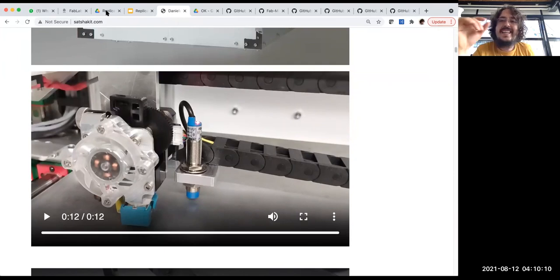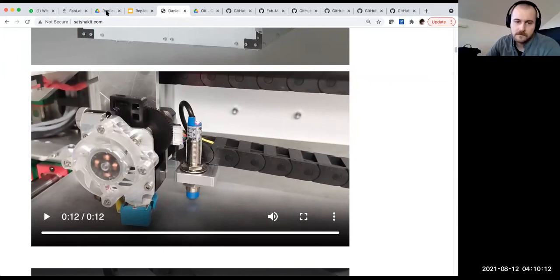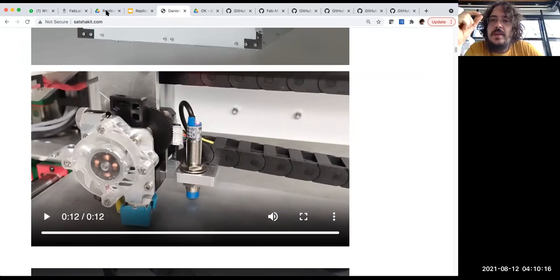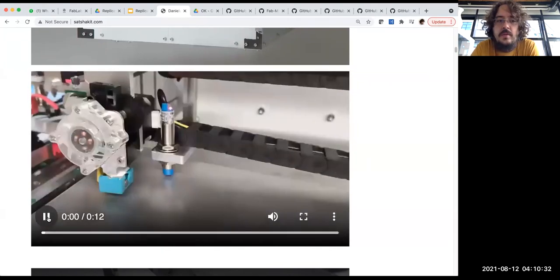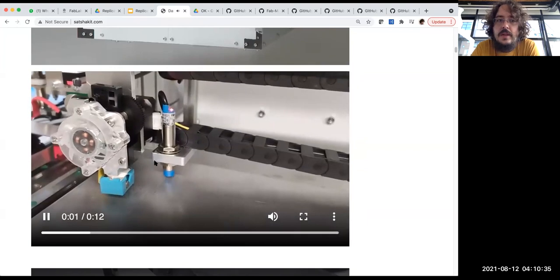The distance depends on the material that you have underneath it, which means, for example, if you use steel, the induction is going to be sensed earlier than with aluminum or copper, for example, because of the different conductivity. So you can adjust this distance according to the material that you have underneath it. But this is something that saved the machine. Otherwise, it wouldn't be able to print.